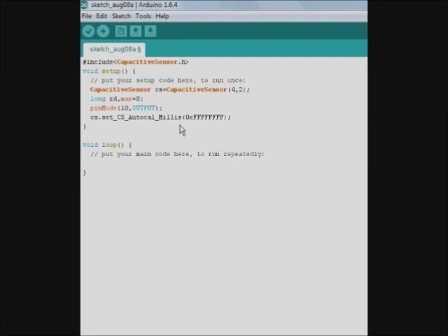What Arduino does is, after a certain interval of time, by default 20 seconds, after every 20 seconds it recalibrates what zero signal means for itself. So if there is some capacitance out there, it will decide that okay, this is 0, and what is over and above is what I have to detect.